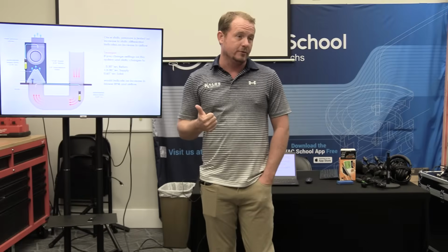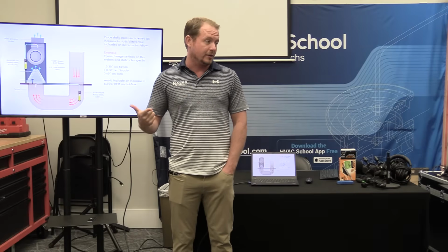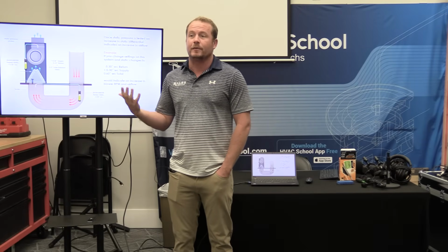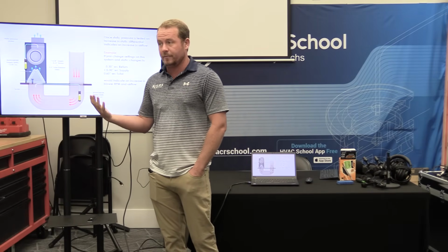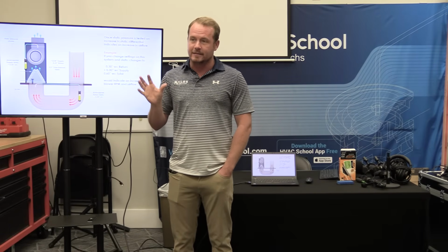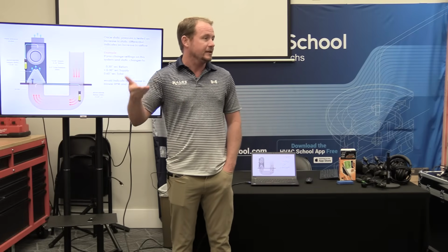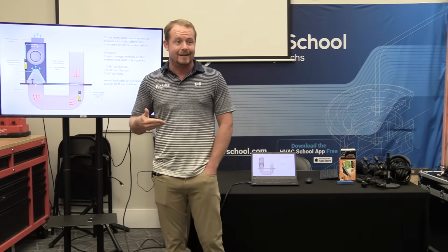So when we commission a new system, meaning when we install it, we do the startup, we're testing it, I want us measuring static pressure on it every time. It can tell us whether we have potential duct problems before we walk away from that. I know it's one of those ones probably when you're in a hurry, job gets late, sometimes it gets missed. But if you know that you've been missing it, you haven't been taking it seriously, please move back into doing it. It's not a hard measurement to take at all.